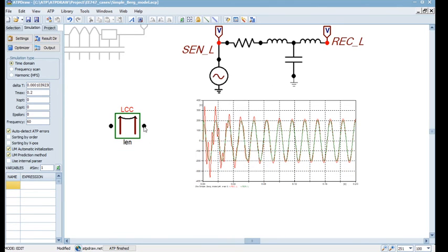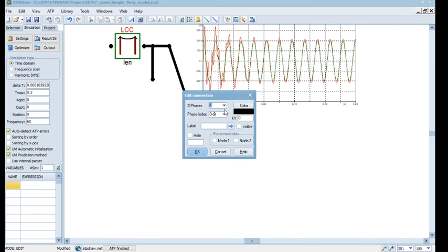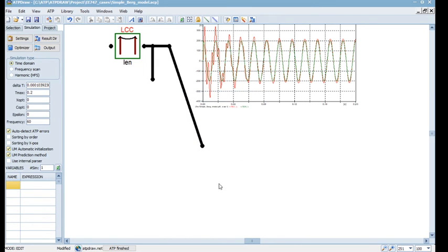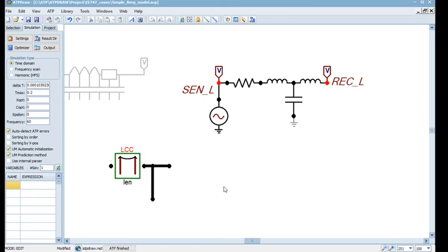Yeah, and since it is 3 phase, let me just show you. If I just drag it, you will see a thick kind of conductor. So always, if you pull it apart anywhere, it will be thick. It implies it's a 3 conductor, and in fact, if you click on one part, you will see it says okay, 3 conductors are available, and so on. So what we'll do is, I think it will go unbound. This 3 phase thing, maybe when the topic comes up, we'll explore again.